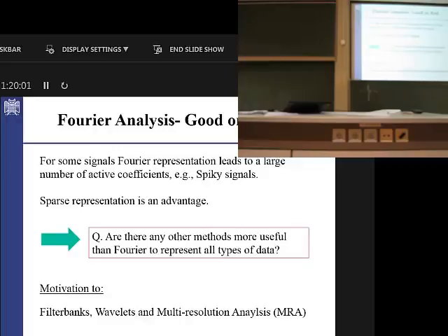But in wavelet, you're not talking about the frequency. You're just talking about the approximation of the signal and the details of the signal. When we say detail, it doesn't necessarily have a one-to-one correspondence with the frequency. But when we say filter bank, we are exactly talking about a band of the frequency spectrum.